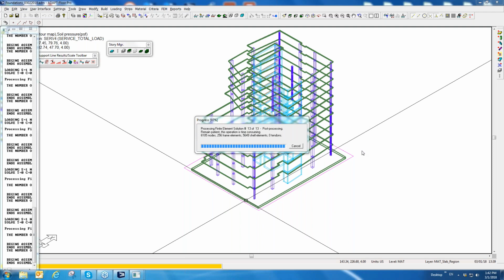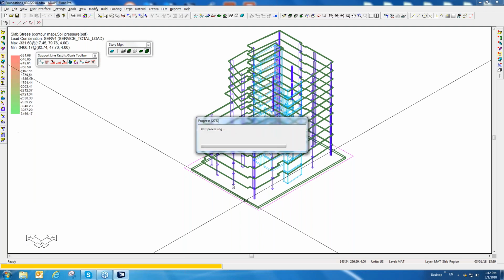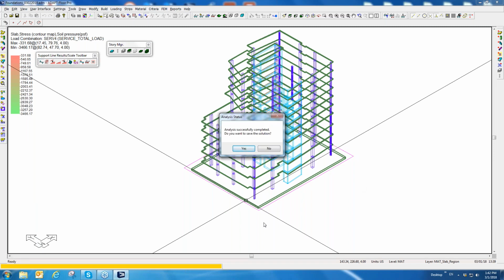So this essentially would become a pile cap at the first elevated floor, and then you model the piles, and the reaction of those columns in the model are your pile reactions. So you would remove the soil spring and you would add the pile, but then what happens there is that it assumes the stiffness of the column based on its length and its properties. So you could try to adjust or calibrate the pile stiffness based on your input.